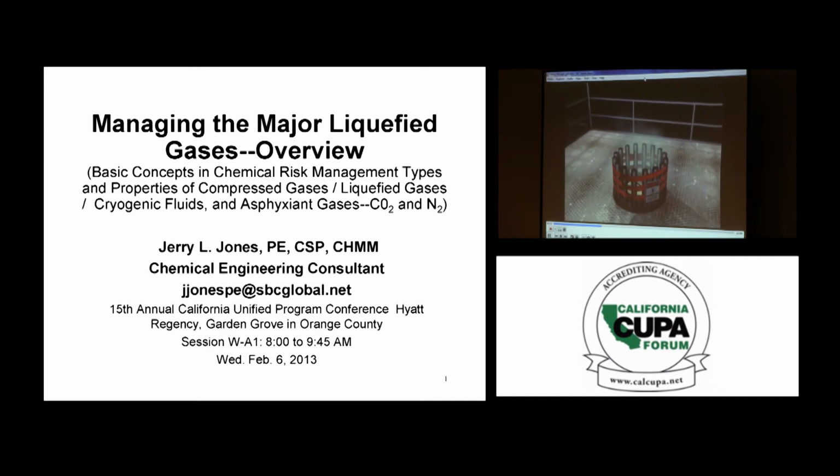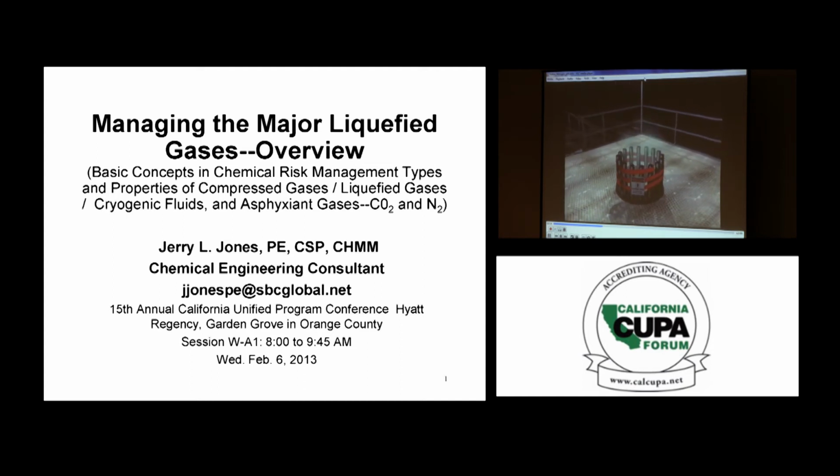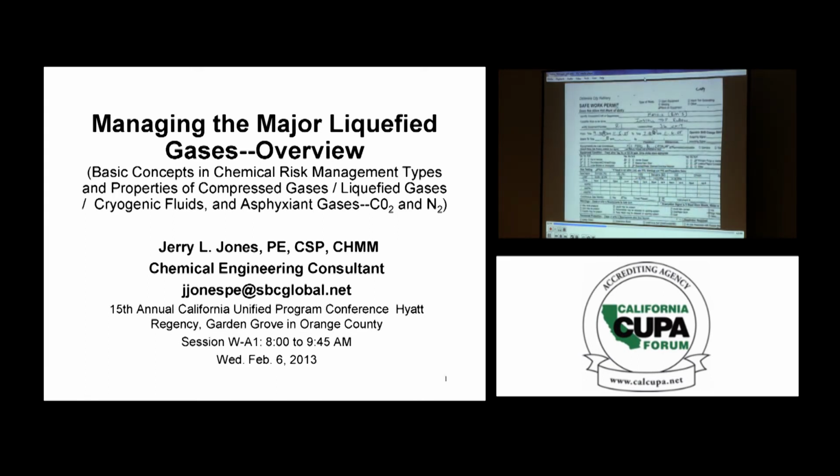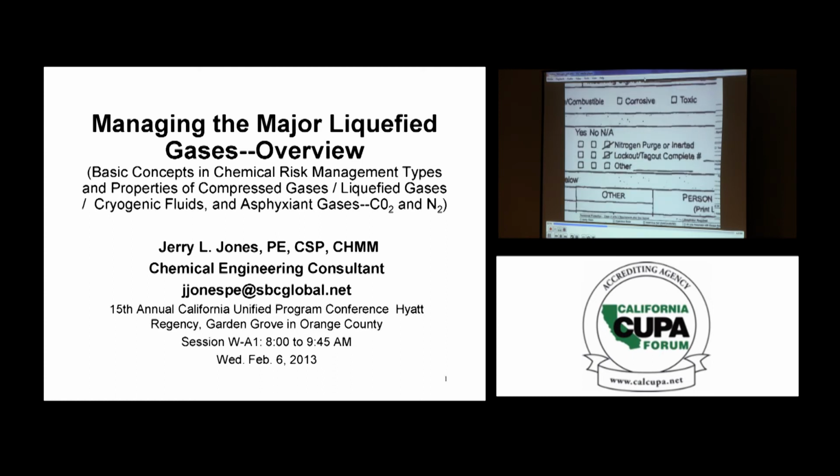Workers had attached a sign reading, "Danger, confined space, do not enter without permit." However, there were no specific warnings posted about the nitrogen hazard. A crew of Matrix contract workers had received a Valero-issued permit to reinstall the pipe elbow. The safe work permit did not warn the crew that the reactor was filled with nitrogen. In fact, the permit stated, quote, nitrogen purge NA, not applicable.